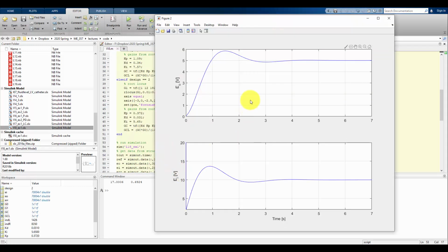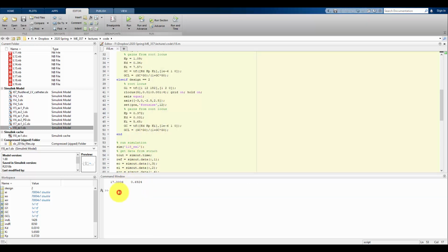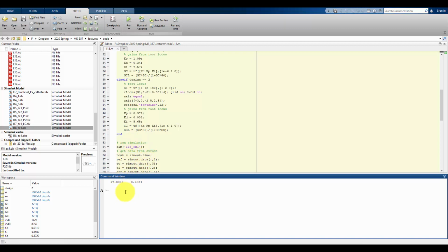All right, so this is what I get out from the simulation. My output voltage, again, I wanted a steady state value of 5 volts, and it does get there. We see that we have our peak, and we see the input voltage here. The peak is at 20, since that's what the limiter was. So it does initially get all the way up to that peak, but then goes very quickly back down to 0, and then kind of smooths out here. So we're going to look in the comparison at how these look. If we look at the numerical evaluation, we see that for this we have a max overshoot of 17%, if we round off a little bit, and a rise time of 0.692 seconds.